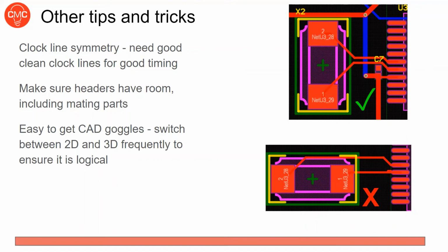One of the things I did when I was first making this board, or actually the ref I gave you guys, if you'll remember, I put the battery connector right below the switch, so you can't actually plug the battery in unless you make the battery connector backwards. Maybe do that better on your board. Maybe don't put those right next to each other, so that you don't have to worry about which direction you soldered in. It'll just work. Things like that. So just look at it in 3D and be like, okay, how am I going to interact with this board? Does this make sense?